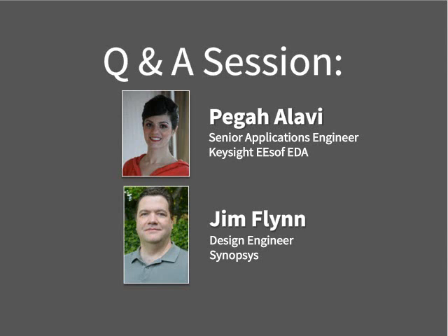As I'm sure everyone knows, PCIe 4 is still a spec that's in development. So we used PRBS11, believing that it is the closest pattern that we could get to our PCIe 4 pattern, and that was the reason that we used it. And it also gave us fast simulation. We could run simulations and lab measurements rather fast. Okay.